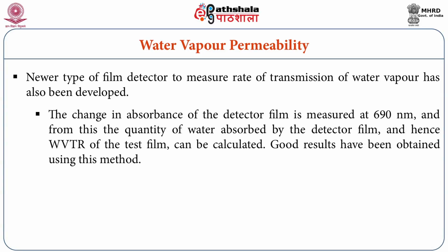The change in absorbance of the detector film is measured at 690 nanometers, and from this the quantity of water absorbed by the detector film, and hence the WVTR of the test film, can be calculated. Good results have been obtained using this method.